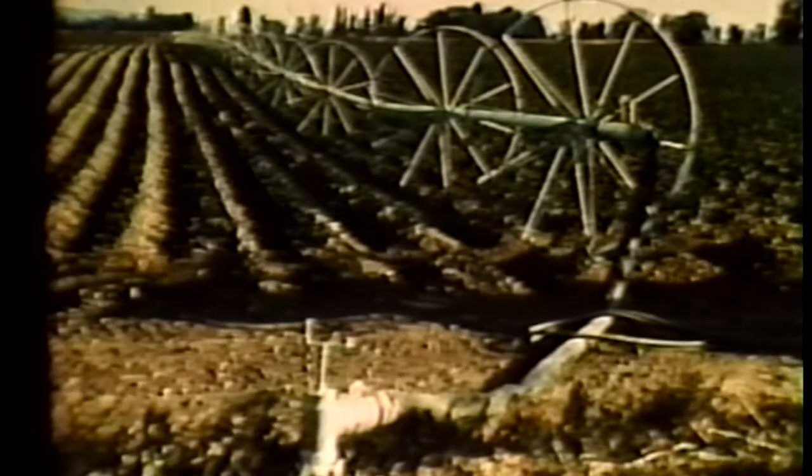The periodic move, self-moved lateral type of irrigation systems are so called because they move from one set location to another under their own power. They are discussed as side wheel roll and side move types. The periodic move, side wheel roll type of system has a lateral made of either aluminum or galvanized steel pipe, which acts as an axle for wheels. The system uses small or medium-sized sprinklers mounted on the lateral, which may be as much as a half-mile long if you have smooth, level land.